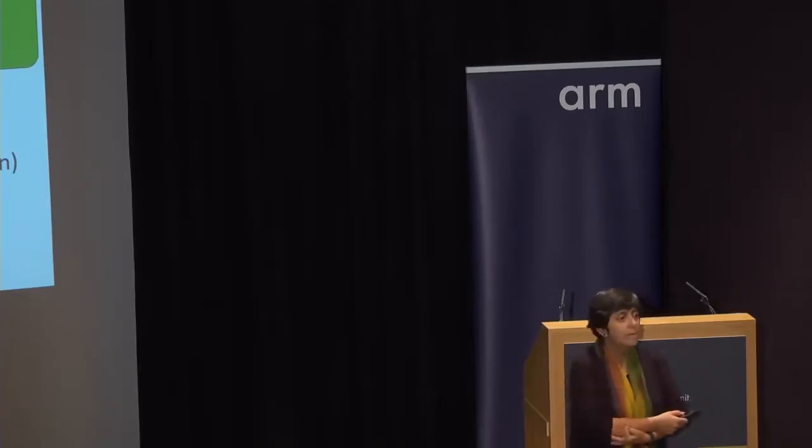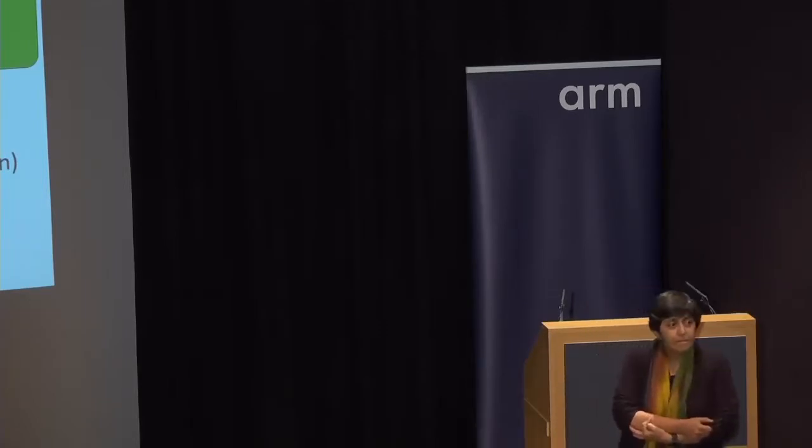So there's the ownership at word granularity. That seems a little bit orthogonal to the rest of the DeNovo or the Spandex protocol. Is there a quantification of how much of a gain that alone provides? Because that would have some overhead in your tags in your last level cache.